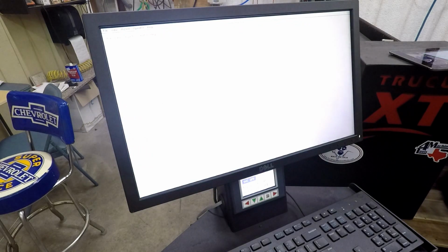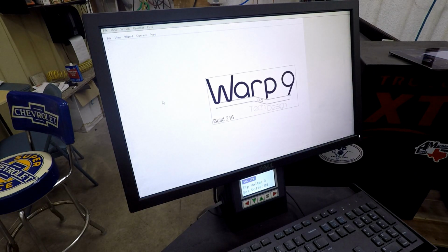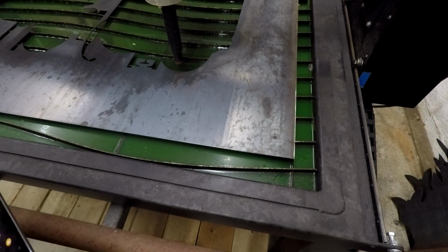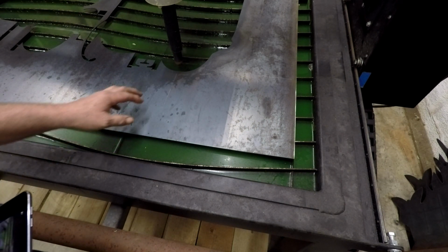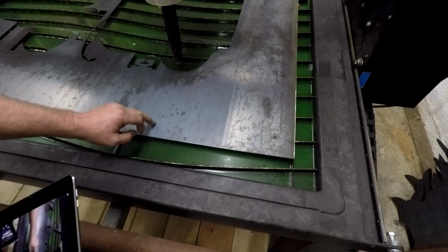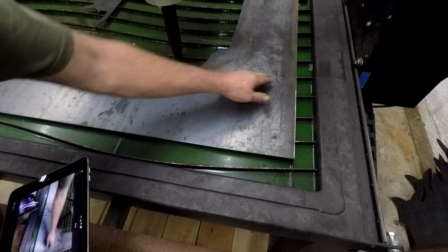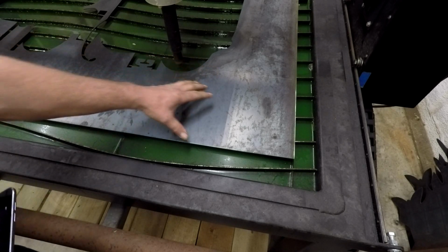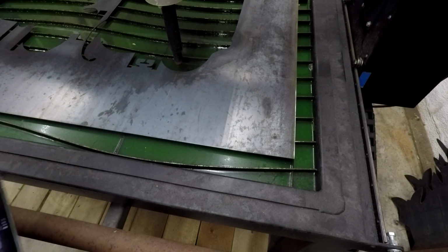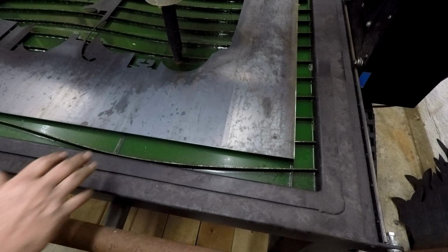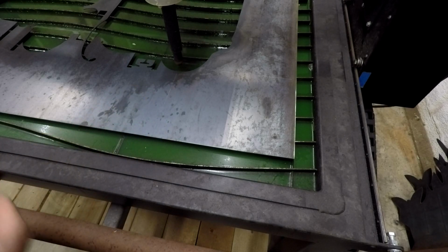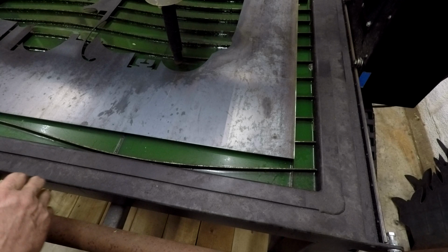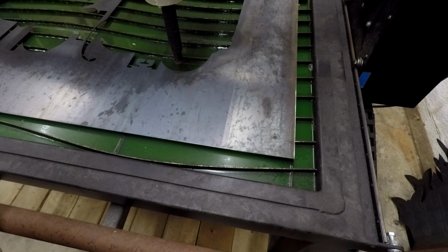So I'm gonna move you down to the other end so you can see what's going on here. Okay, so I've put me some marks right in this corner where I want to line up, and I've lined the torch up on the X and Y there. This piece will barely fit in this spot, so it should have plenty of room, but anyway, I'm going to go down to the machine down there and get ready to set this off. All I got to do is load that file we just made into Mach 4, and I'll set that off.